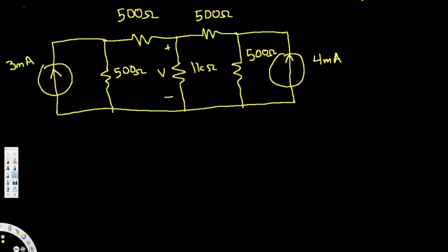In this video we are going to see how to find unknown voltages using the nodal analysis method. In order to do nodal analysis, the first thing we have to do is connect this bottom to the ground. That way this is going to be 0 voltage, and for the other nodes we are going to give V1, V2, V3, something like that, right?